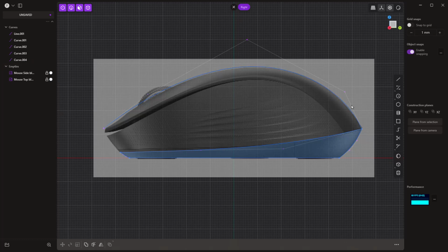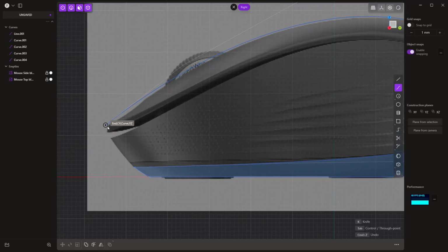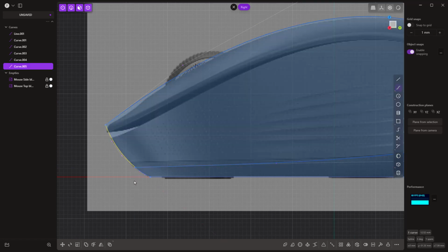So depending on your needs, depending on your requirements, just pick one or the other is fine. But just note that after we're done with the traditional spline, Plasticity automatically adds these external control points for us. All right, the last thing that we're going to do is we're going to go from here, hold down Control, put a midpoint here, let go of Control, and snap to there.